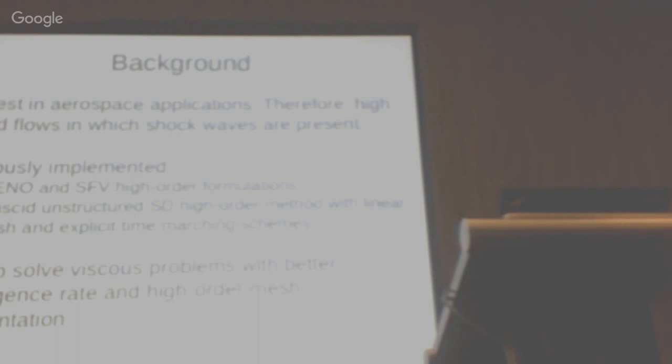As I told you earlier, all of these extra methods and schemes are necessary for an effective high order solver. As stated, you need high order boundary representation to maintain the high order of the reconstruction. You also desire an implicit scheme to allow faster computations and realistic analysis and performance. And as the title said, if you want to deal with compressible flows, you want a limiter appropriate for these kinds of methods. You don't want to rip your high order reconstruction out of the domain.